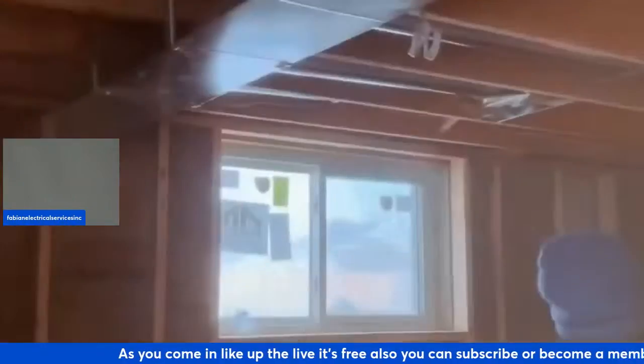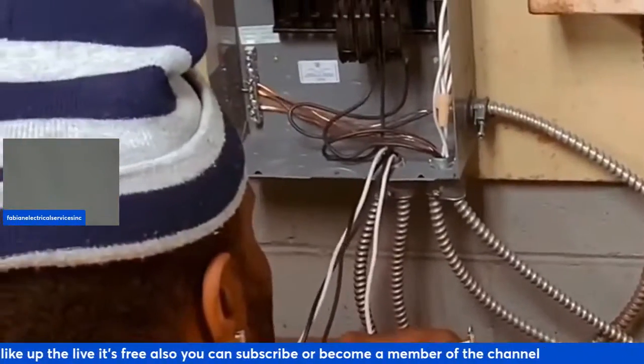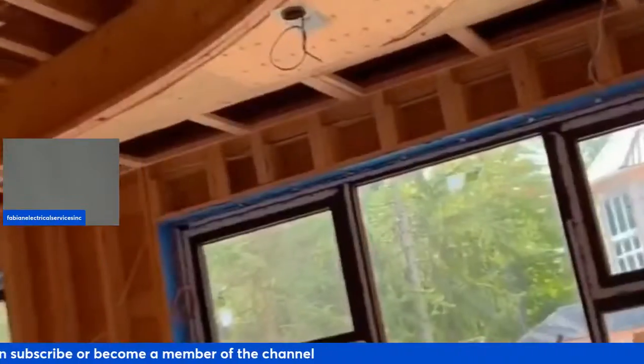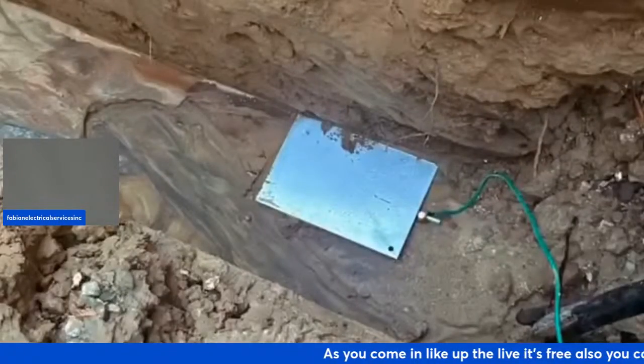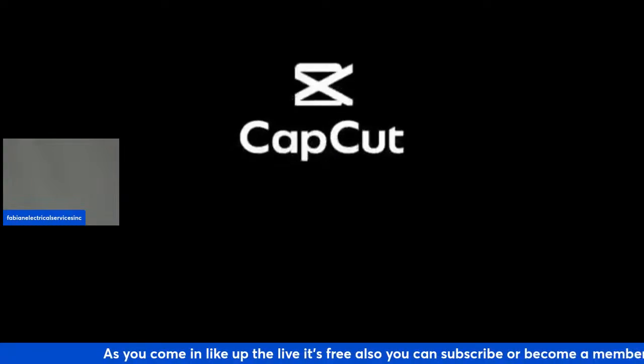Again, it diverts excess energy when a power surge occurs. Internal components, most commonly metal oxide varistors or MOVs, conduct the excess current and divert it to the ground wire instead of allowing it to flow to your electronics.